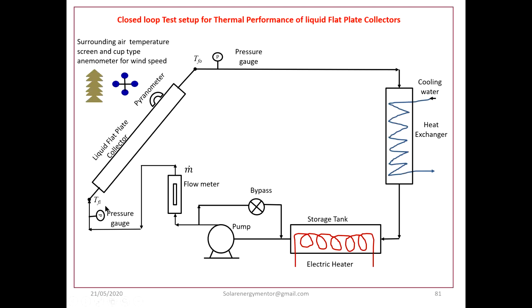So if we want to design the fluid inlet temperature as per the requirement, then this storage tank and electric heater will serve the purpose. For example, in the normal case of radiation, the fluid inlet temperature with water may not exceed 60 degrees Celsius. But then that limits the test range. But this collector has to be tested.